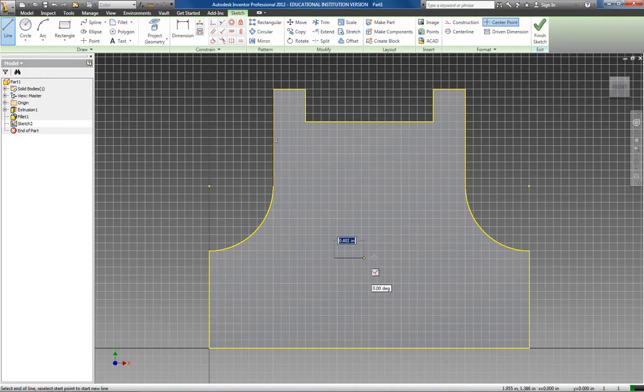So I'm going to left click from here to here to draw my line, and then as I come back over the end point of this line, and instead of the little yellow dot that follows my cursor, it should turn gray. Once it turns gray, I'm going to left click and drag an arc off of that. And I'm going to bring that out to meet up with the other end point, and then left click and drag again to actually create the flat oval. Now there's some things in here that need to be addressed, which I'll get to momentarily.